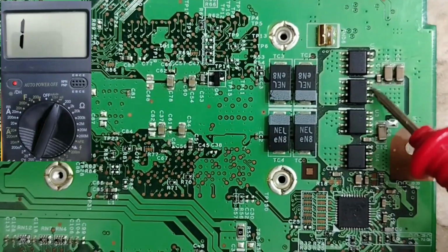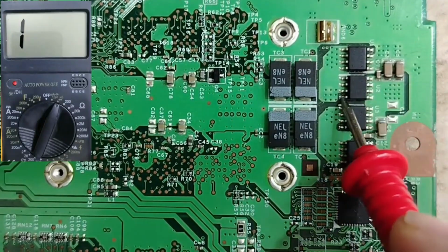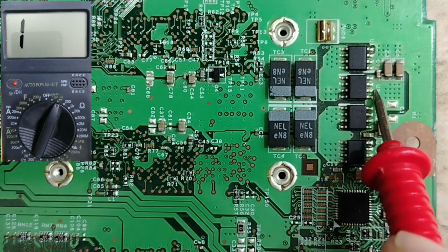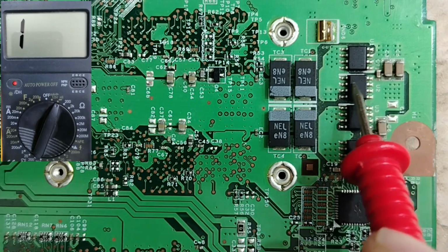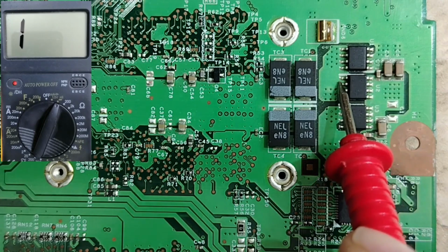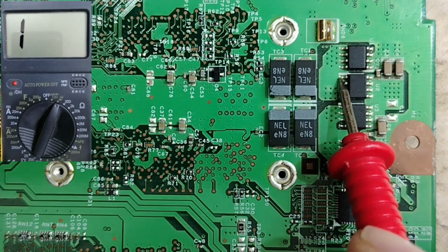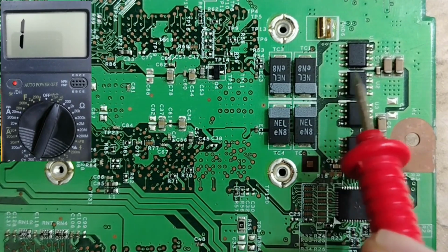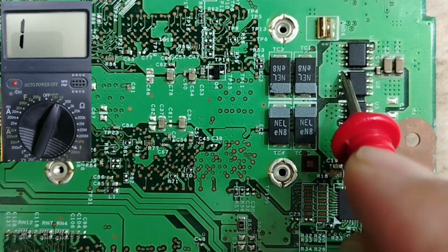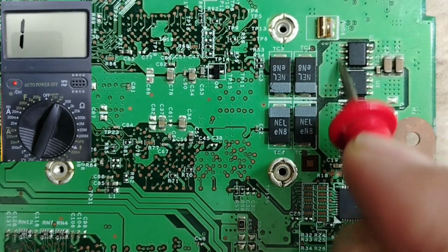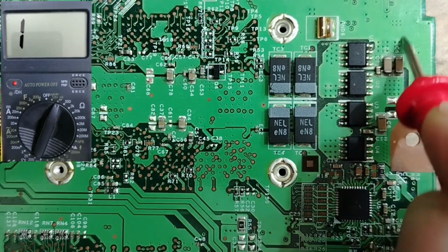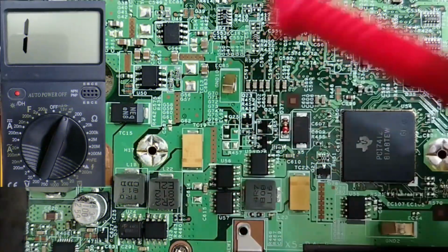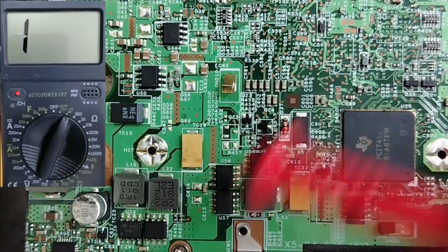So the 19 volt will pass to the drain, and then after receiving the control signal here in the gate from this IC, this voltage, the 19 volt, will be transformed to plus VCC core. So VCC core is about 1 volt. Basically, it is between 0.7 volt and 1.5 volt. Do you see? The source of this MOSFET is connected to the drain of this MOSFET, and then this MOSFET is connected to the ground.